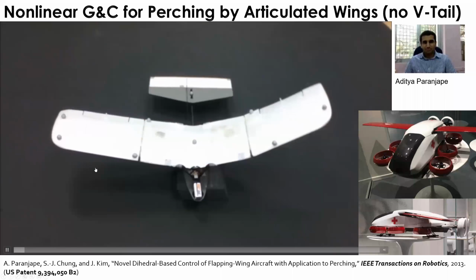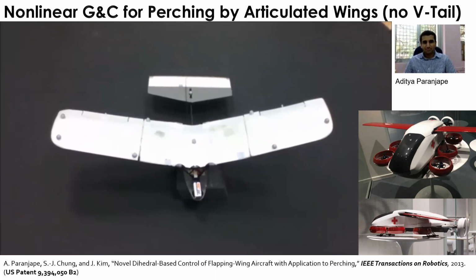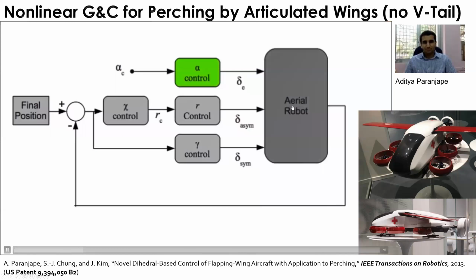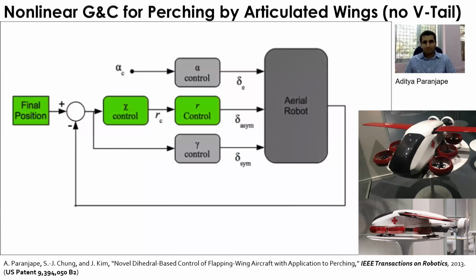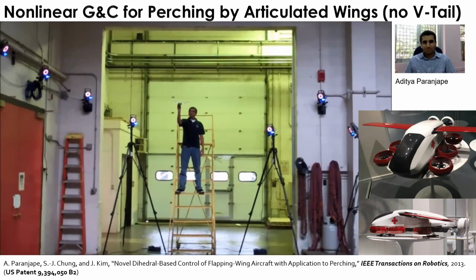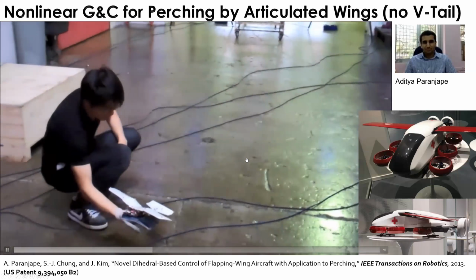One example is this particular aircraft inspired by bird flight. As you can see, this one doesn't have a vertical tail. If you know flight dynamics, without a vertical tail and rudder you cannot really control the heading, or yaw, or directional motion of your aircraft. Also, you have less stability because you don't have damping in the heading motion. So, to demonstrate the capability to perch on a human hand.